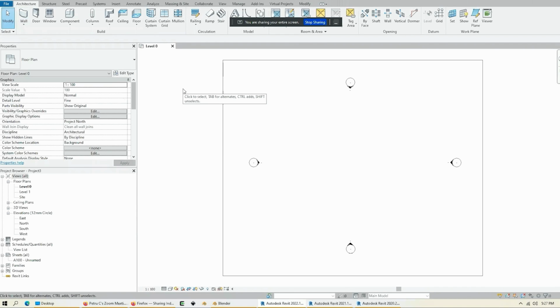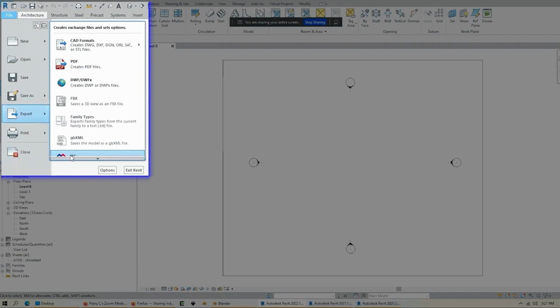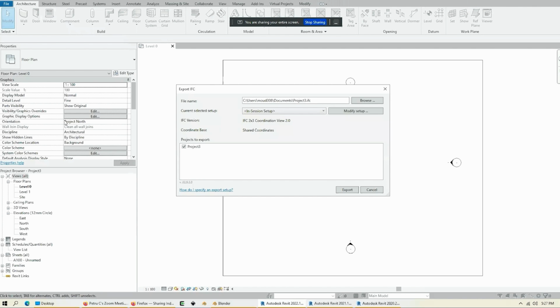So the very first thing you want to do is make sure that you have the right IFC export add-in. Most Revit users, if you just go to File and Export an IFC, yes, you can export an IFC, but actually the version that comes installed with Revit is very likely an extremely outdated version, which has many bugs and problems. And I won't list them all today. We're going to be nice and snappy. I'm just going to say you have to upgrade to the latest one.